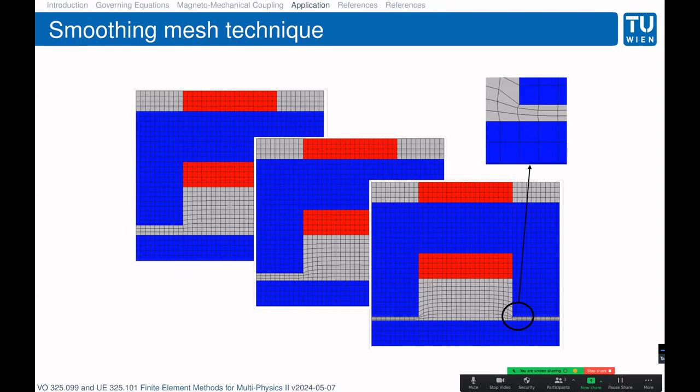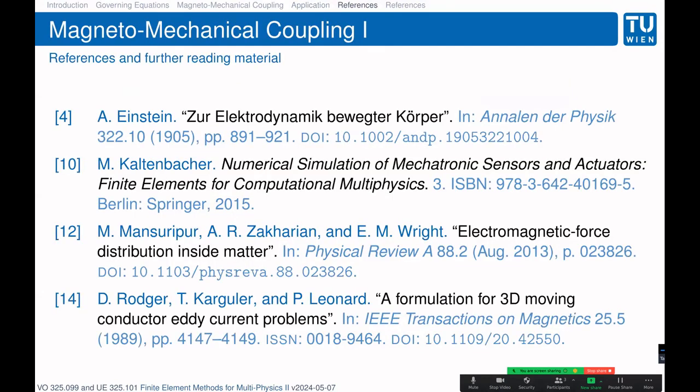If you would imagine, okay, I take the material properties of air and of steel and I put them into the same monolithic system matrices, you get very low stiffnesses of, so to say, the unimportant air region that can destroy the conditioning of the mechanical system you actually want to compute. This is the reason why splitting this into two different PDEs is an advantage. Yeah, finally,